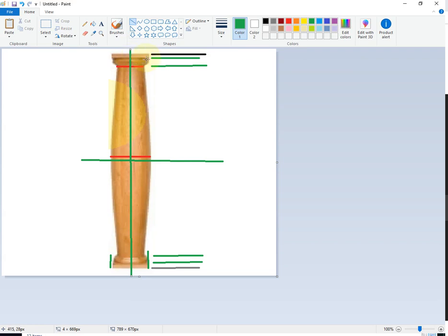And then for this detail, it looks like it has a little bit of a chamfer and then a straight edge. So basically, we'll be drawing a shape that is sort of like this, granted, it'll be a little more straight, and then revolved around an axis here to create this little chamfer.